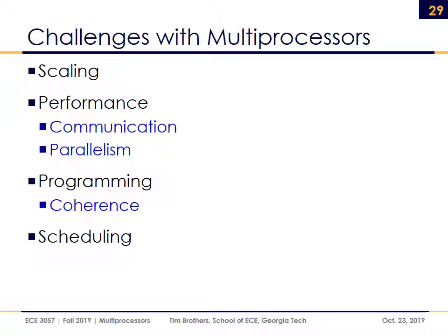So there are some unique challenges with multiple processors that we don't see in a single processor system. How do we scale it up? As we saw in the last slide, we have the shared L3 cache. That has now become one of the main areas of the core of this chip. The space consumed by the L3 cache, which has to have connections to all the processor cores, is now becoming a major part of this chip. So how do we share that as we get more and more? Because the interconnections are going to build up to be very dominating on this chip.